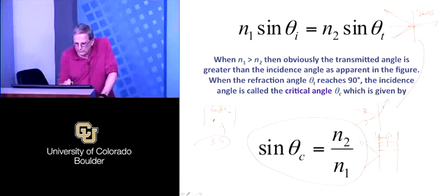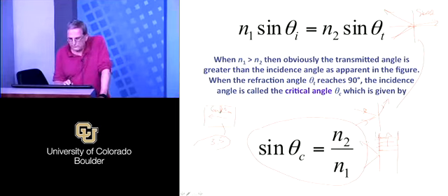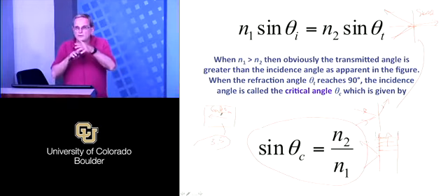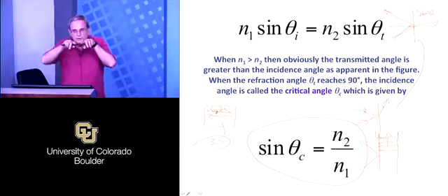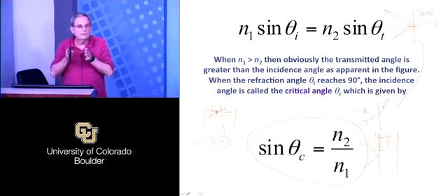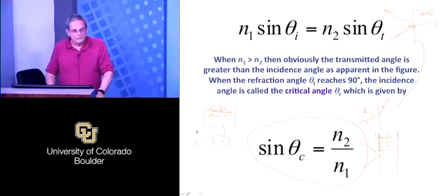That's also one of the reasons why when you have semiconductor lasers, you don't actually put mirrors on them. The reflection, as we find out from this, is something like 40%, and you aren't losing many rays because rapidly they get damped. If they get off axis, they get trapped. So the actual cleaved semiconductor itself makes a pretty good laser cavity if you can cleave these things pretty cleanly.